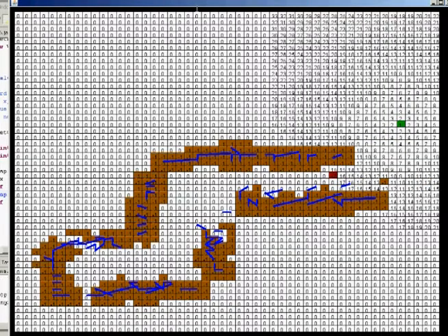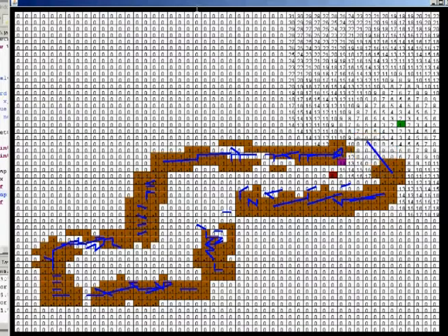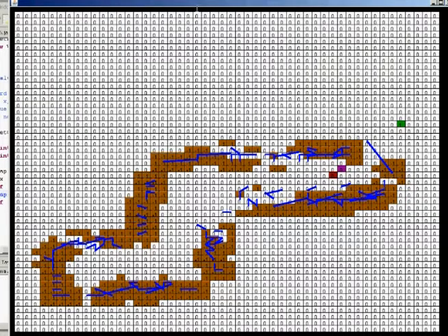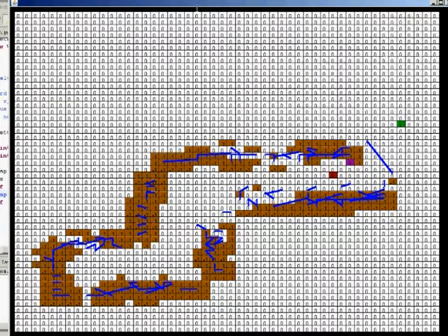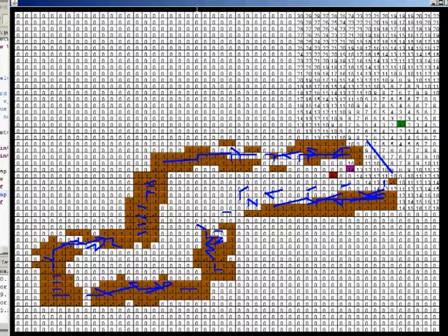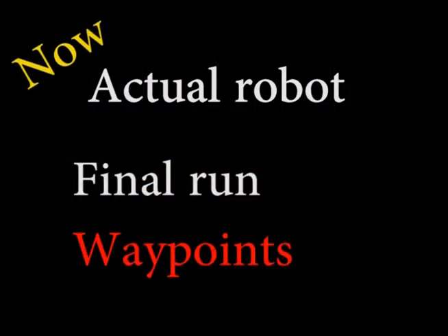For the local map, we use an IR sensor, mounted on the front of the robot. It sweeps from -90 to 90 degrees from the initial sweep, and that scans pretty much every wall surrounding its front and back. Because the sensor is on a servo motor turret, we know the exact angle of the encoder. That way we can also figure out the exact location of the wall given the distance that the IR sensor returns, and that will determine the location of obstacles and walls, and then we can update that to the global map. We'll talk about how they update to the global map.